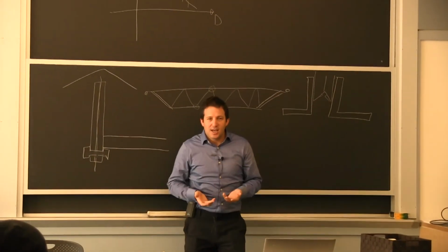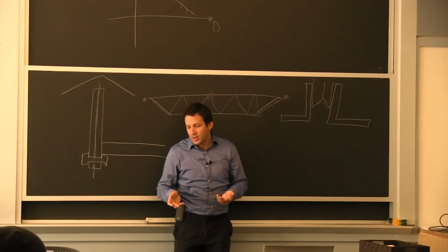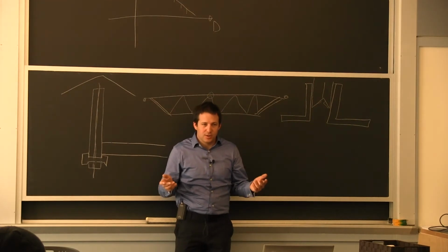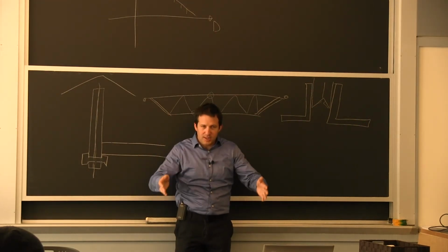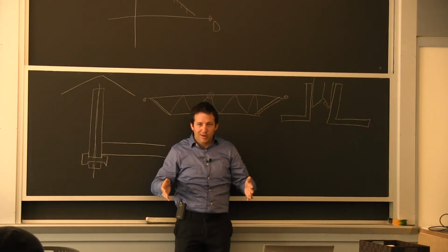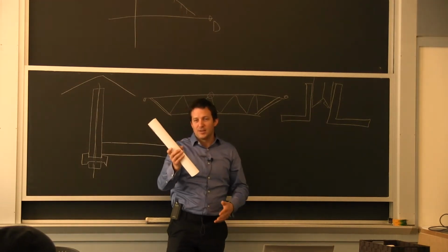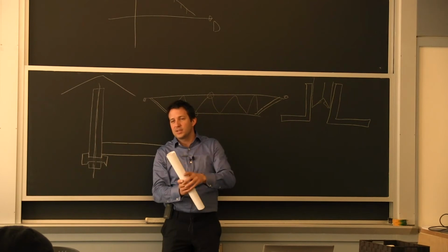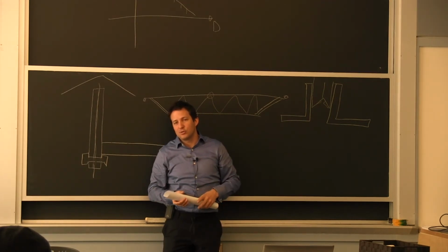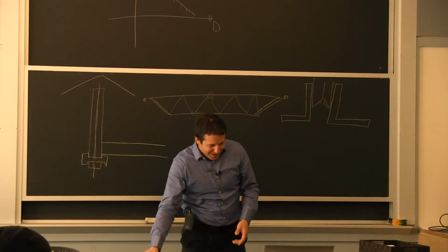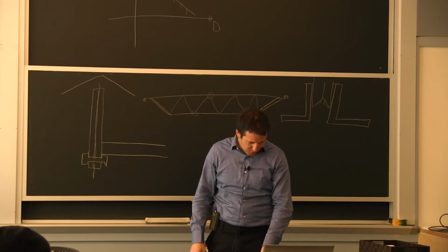And in a lot of buildings, they do that for bracing connections. They try to put everything square, but there's always going to be some deviation. So when they come with the diagonal, they love to be able to weld it because they don't need an alignment of the holes. It's very simple, but that's how it works.